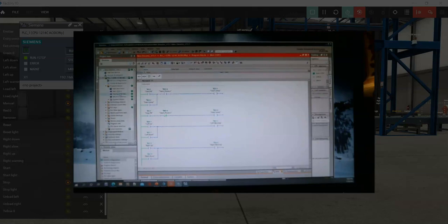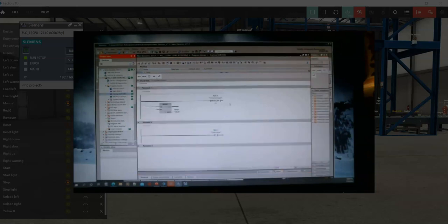So we have this little startup block, and what we do is every time that we go from run to stop and then back to run, we put the outputs in a known condition. So this is saying that we're resetting, and it looks like it's really hard to read, but we're resetting the outputs starting with the first output and resetting up to the next 28 outputs. That's what that says. And then it also says we're starting with our mode at 0, and the only one that we're setting is the stop lamp. So when we get into the right condition, the only thing we should see is the stop lamp turned on.